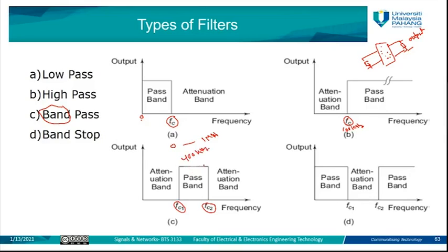In this case, I have to use such a band filter because I know the minimum frequency, 400 kilohertz, and the maximum frequency, 600 kilohertz. So in between these values, all the signal will go through our system.